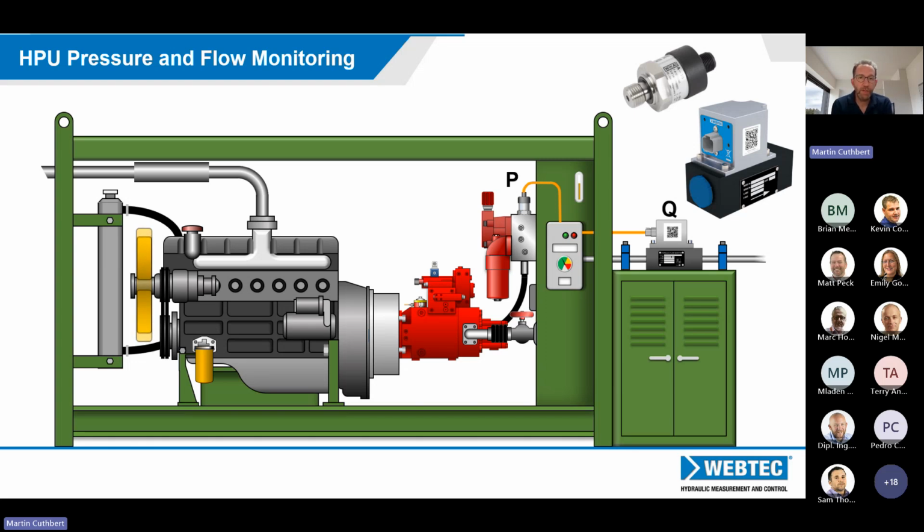So this is the compact heavy duty turbine flow meter. It gives you a little bit more accuracy and would allow full bidirectional measurement. And their signal, as we mentioned before, could come out via 4 to 20 milliamp or CAN J1939.